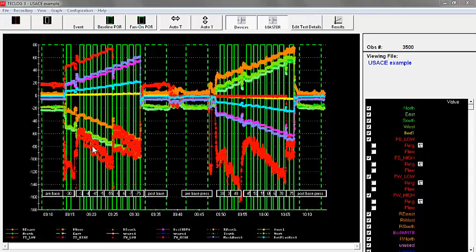Our reds are our fan pressures here, so we can see we're depressurizing. Our greens are our envelope pressures, and then pressurization. So baseline, 10 fan-on periods of record, another baseline, and a second baseline for pressurization with 10 fan-on periods of record. So first, we'll look at just the second baseline period of record.